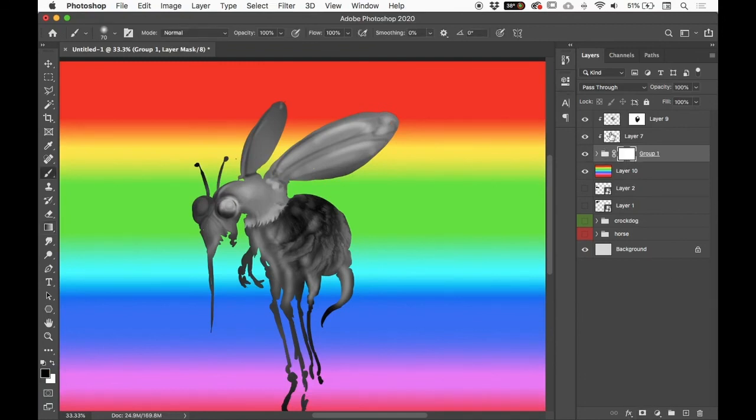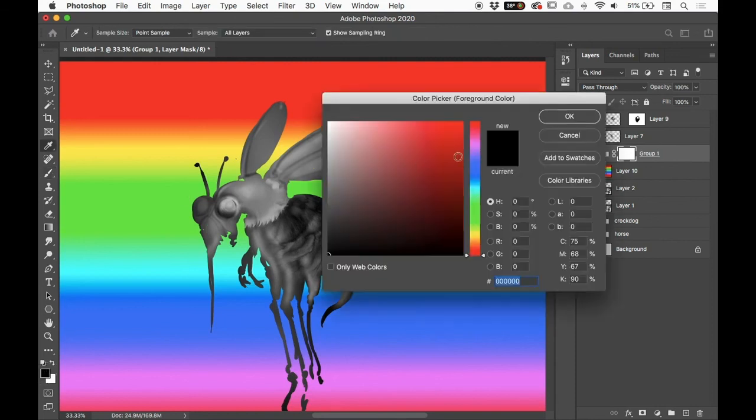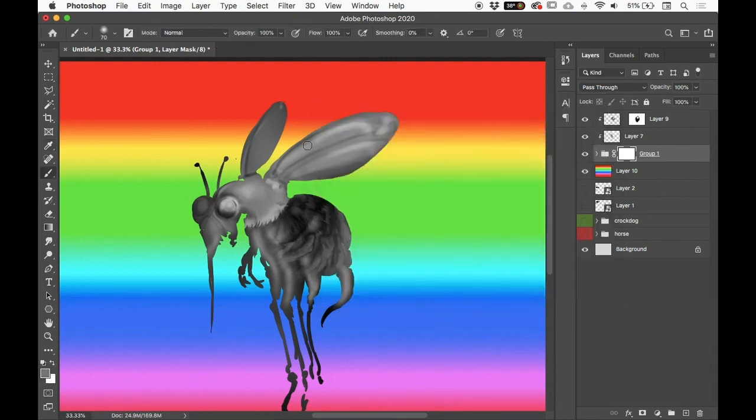And once again, I'm going to use B for brush in this instance. Could use lasso as well, and black is going to be invisible. So if I actually start painting that invisible, it's going to make that erase from my object. If I lower the opacity of that, or keep the opacity up and go for about 50% gray, that means that's at a maximum that's going to be 50% transparent. And of course you can vary that, so the lighter that is, the less transparent it is.